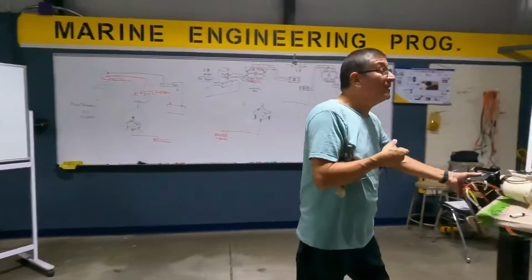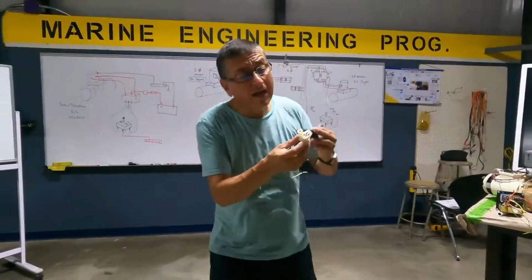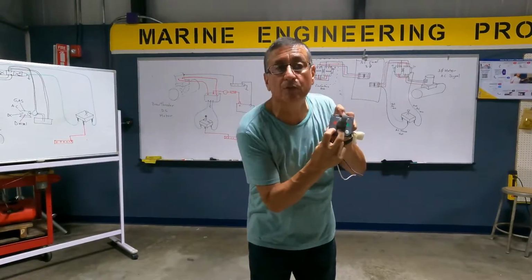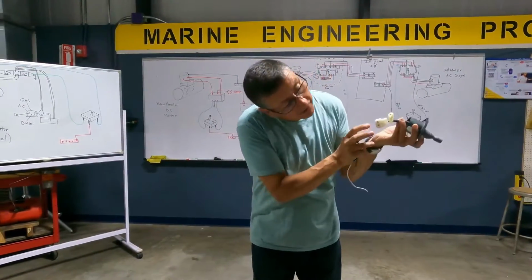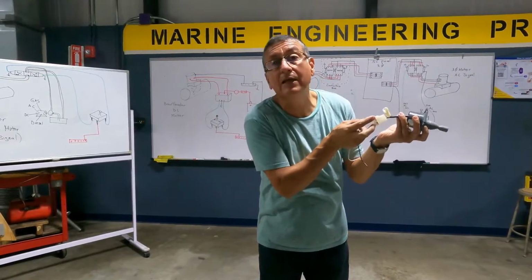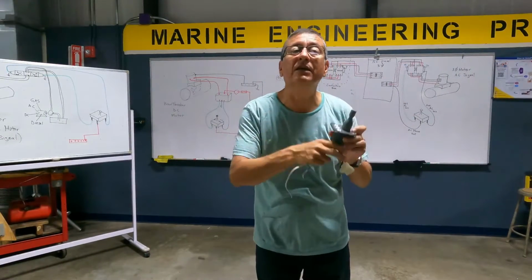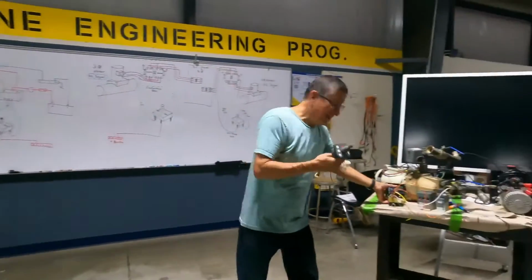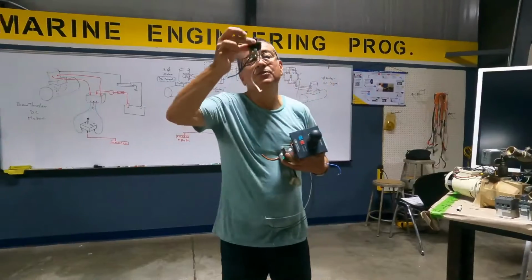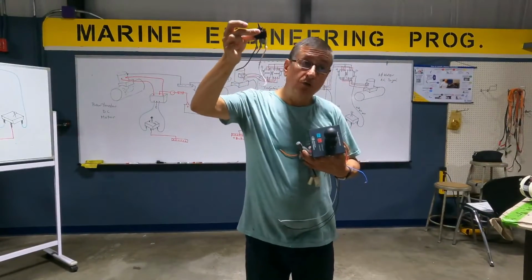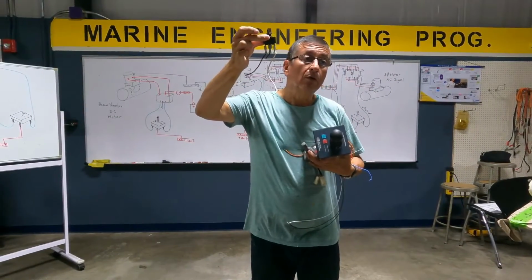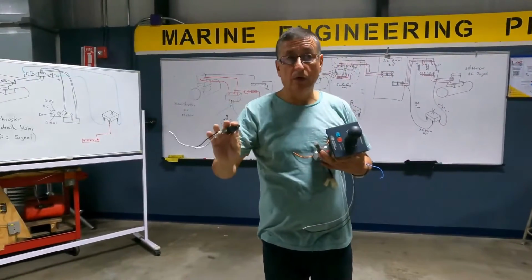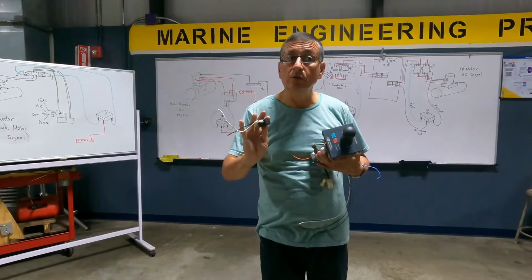All right. This is exactly the same. I have 4 terminals here. One power and power, because I have light here when I turn it on. This diagonal is the power, and the other diagonal is signal for one side and signal for the other side. This is exactly the same as this one, and exactly the same as this one. And all continuity can be checked without power on that one, correct? Without power. Check continuity without power. Always, always. That's clear, no?